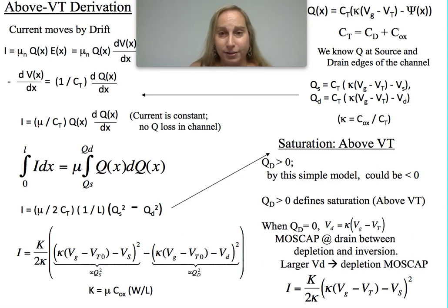Well, if I look on the other side here, we can talk about the charge anywhere along this channel, and at this point we're assuming that it's inverted all the way along the channel for this conversation. That is an assumption, right? But from the source to the drain. And so what we'll be imagining is that the charge all the way across will be related to the gate voltage and the surface potential. And in fact, there is a direct capacitive coupling. There's also charge that comes from the surface potential down to the substrate, which we're assuming is at ground at this point for a typical NFET in a typical N-well process.